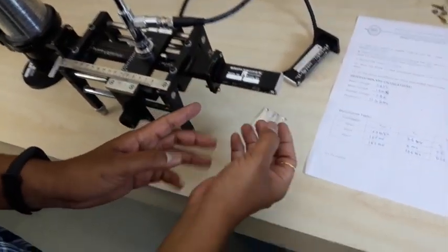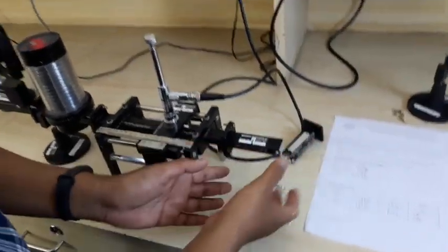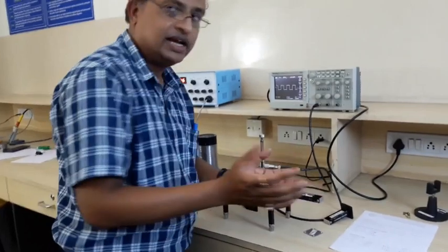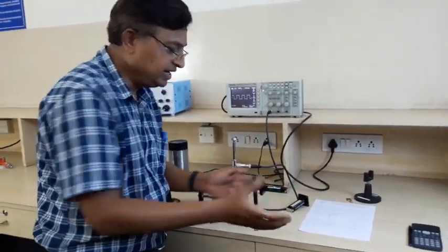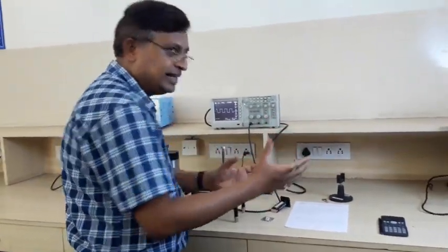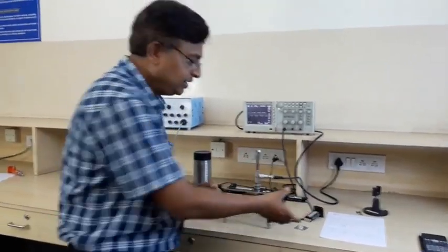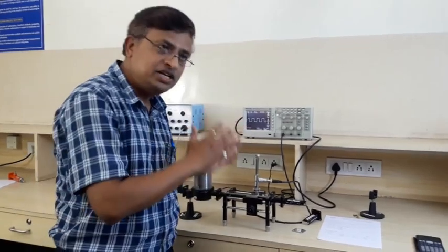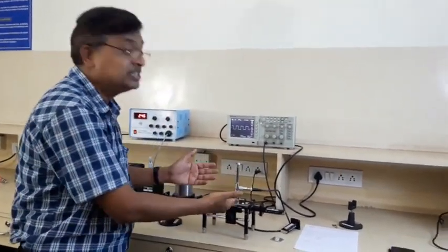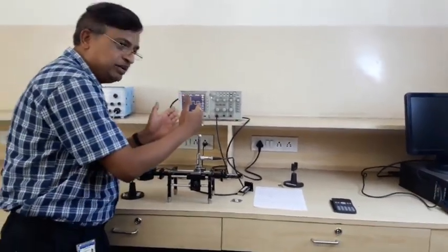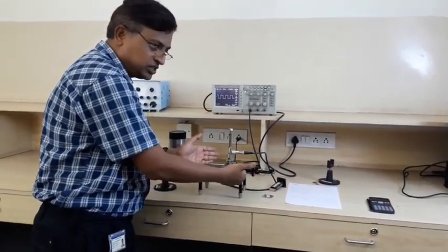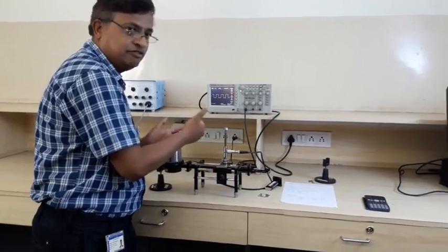Similarly, as I have connected the match load, the open condition and the short circuit condition, one can directly connect a waveguide horn antenna as a load. I can calculate that horn antenna impedance by measuring VSWR with the similar procedure: connect the horn antenna as a load, move the probe to get Vmax and Vmin.